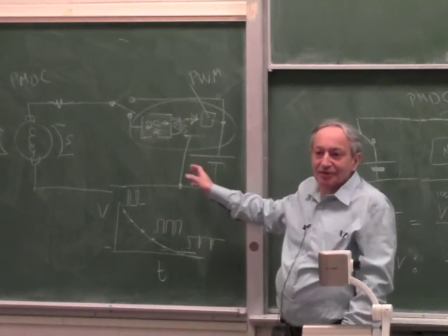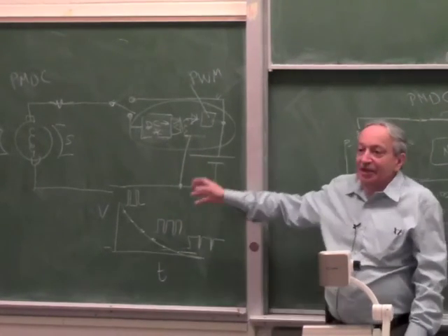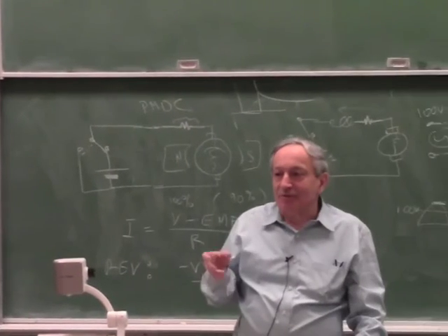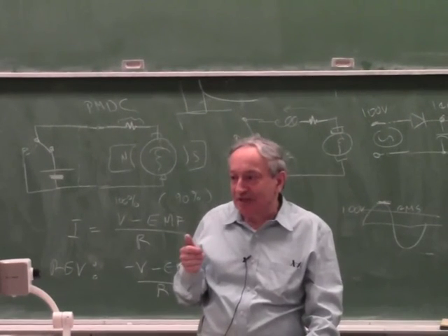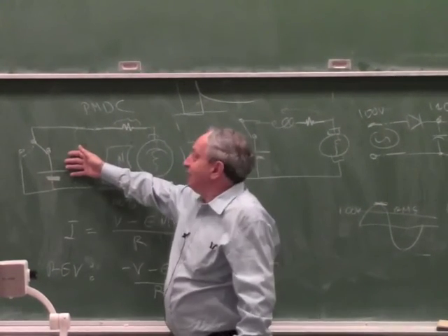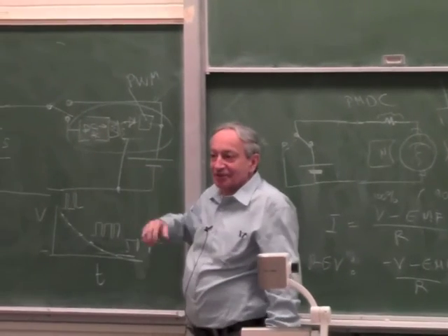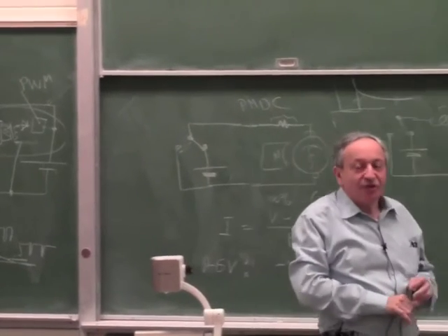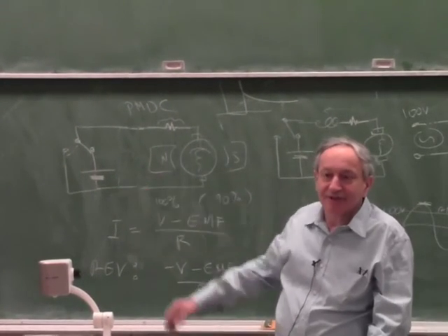Is that clear to everybody? Good. So that's basically how dynamic braking works. This is how it works in your bicycle when you have some new electric bikes that have dynamic brake, regenerative, not just dynamic, regenerative. When you say dynamic, you just mean this typically. That is called dynamic braking, and that's called regenerative. You actually put the energy back in the battery. Okay? So of course in electric cars that's critical to get the maximum range.